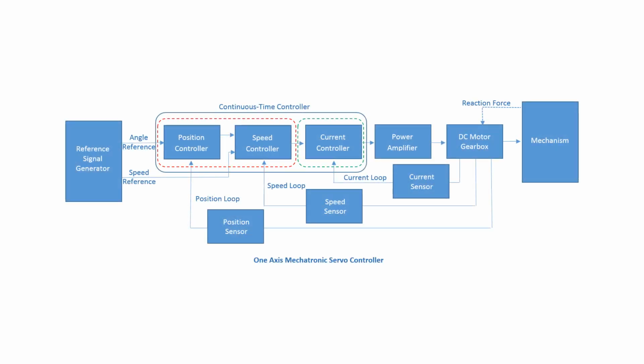This figure shows a typical architecture for servo systems. The block with green color is the controller part already built, and red-colored blocks are to be built in this stage. This feedback control system has three control loops. Current loop, inner: it controls the motor current and, therefore, the DC motor torque. This control loop has already been developed and included in the power electronics behavior model.